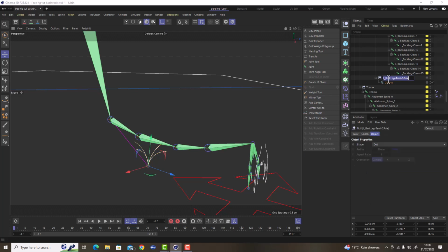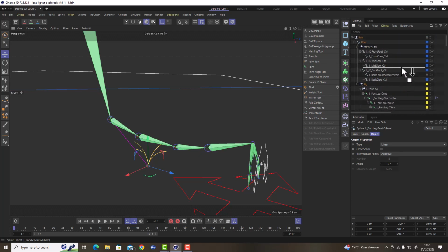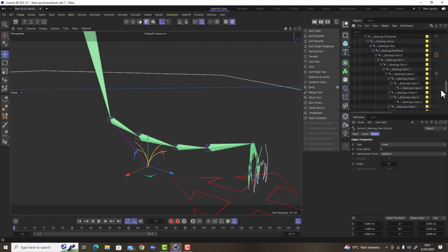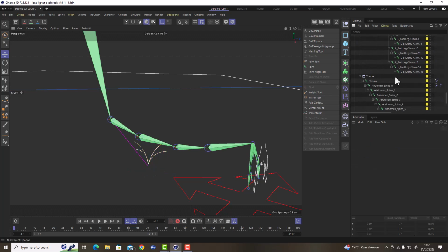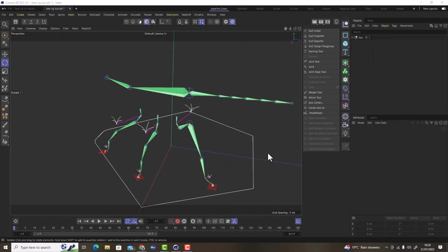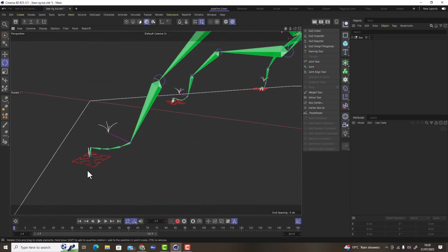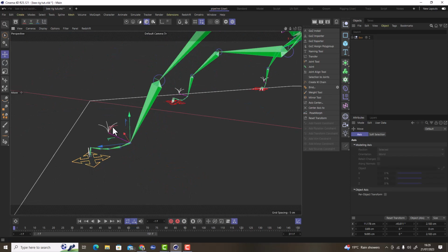I'm then going to copy this naming, put it into there, paste, drag that up where it does belong. And this is the claw part of it, so we've got that pole for the foot IK and that pole for the claw IK. Remember to go back and clear anything that we don't need anymore. And now we've got those two poles there. When we finally complete it, it will look like this. You're going to have everything set up in a way in which we've got the IK all working for us the way that it should.